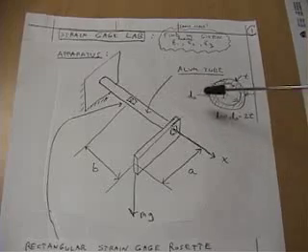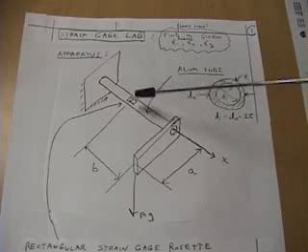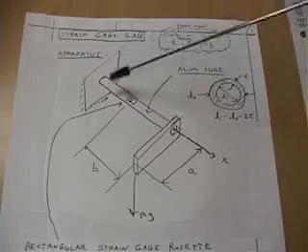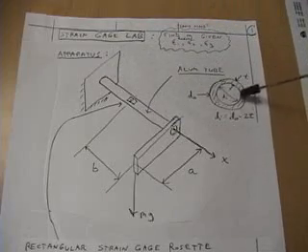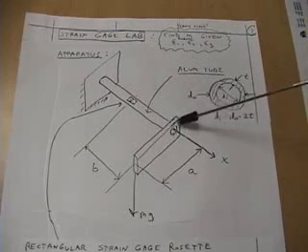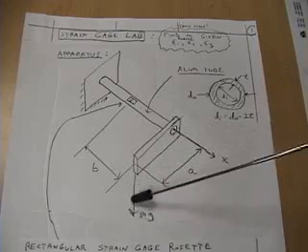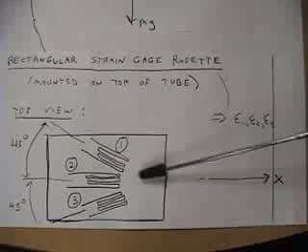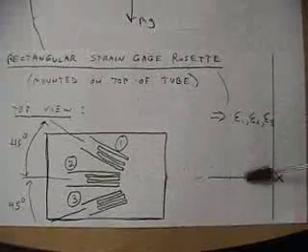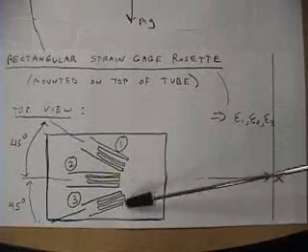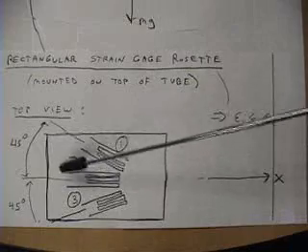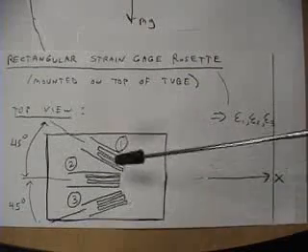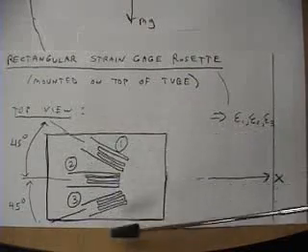This figure illustrates the apparatus used in our strain gauge rosette experiment. We have an aluminum tube with a given cross-section, and we have an offset load where we apply a mass hanging from the end of an arm. The rosette is oriented on the bar, where X is the axial direction. It's oriented like so. 3 gauges are 45 degrees apart, and they're numbered 1, 2, and 3.